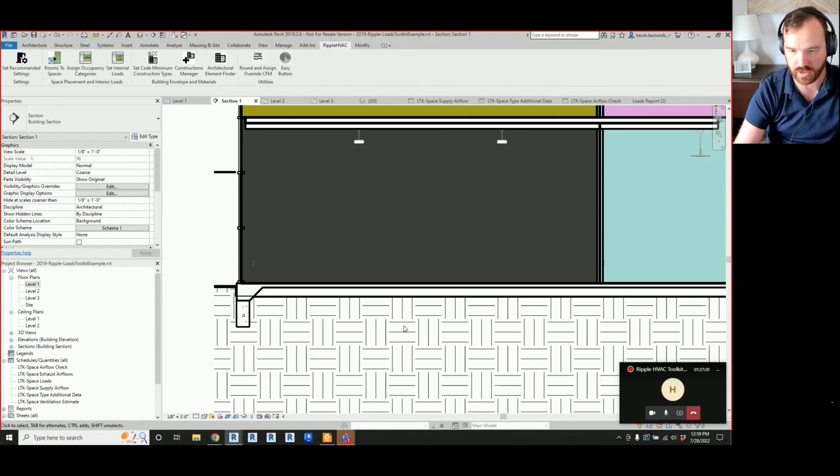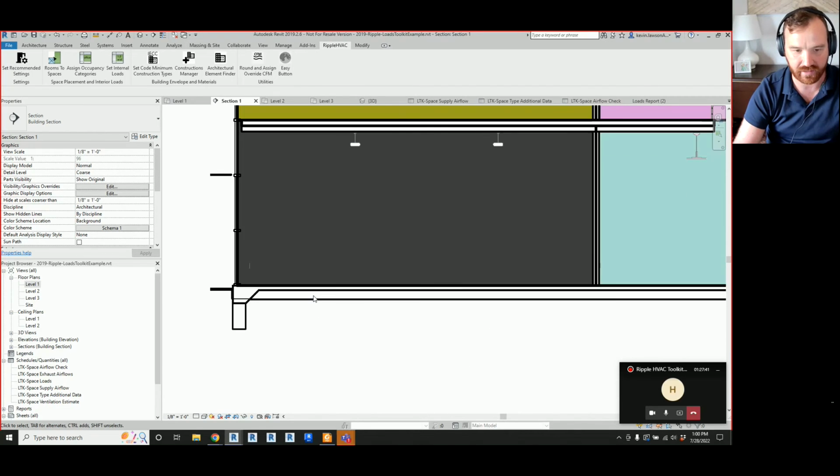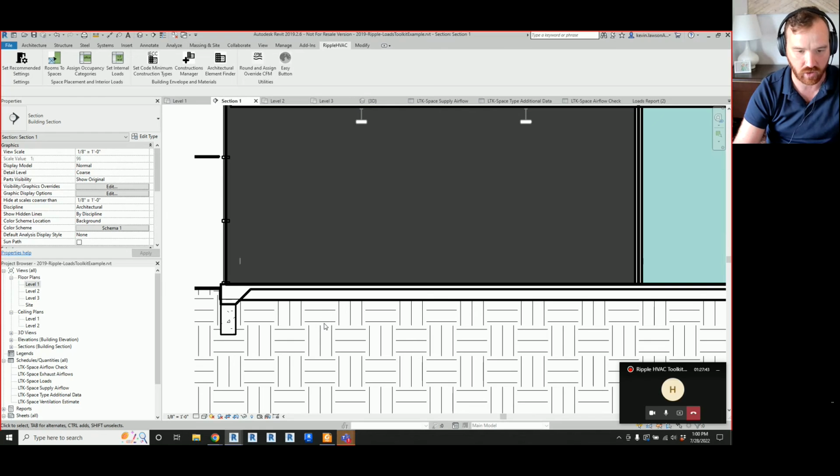My opinion on that has always been, what's the lowest temperature that this ground can be? And it better not be below freezing, because if it's below freezing, this is not a slab. This is just going to be rubble in too long. You're going to have frost heaving. So the delta T between these should never be too great, and it's always just going to add heating load.